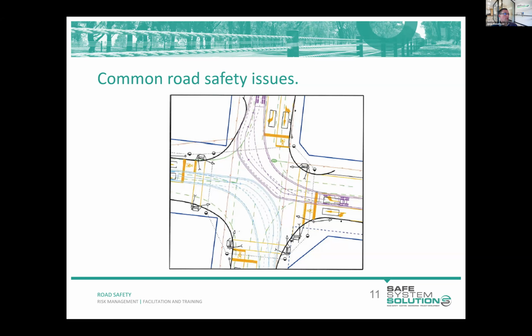And then the parallel solid lines on either side represent an additional clearance to the vehicle body. The Austroads guides talk about providing a 1/2 metre clearance between the vehicle and any roadside objects or curbs. So that's why that additional line is usually shown or should be shown.